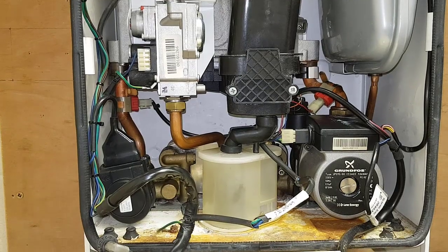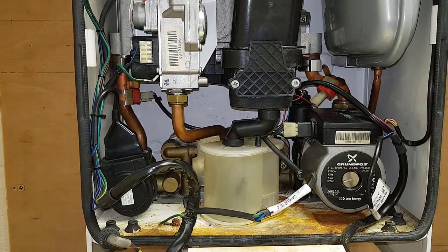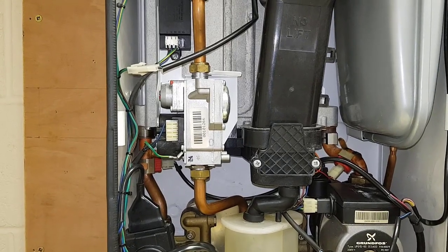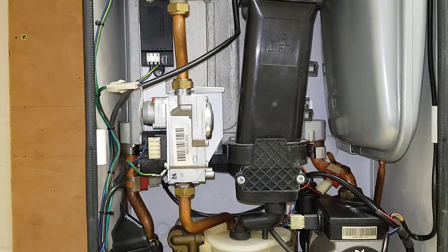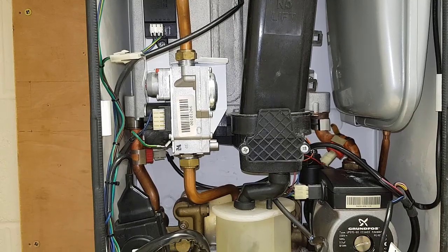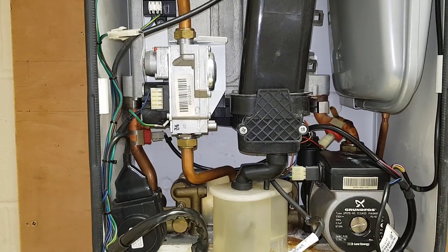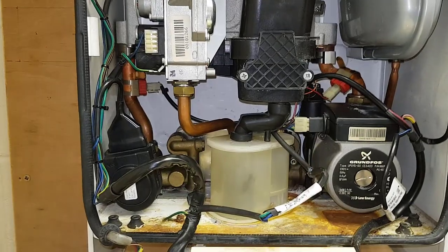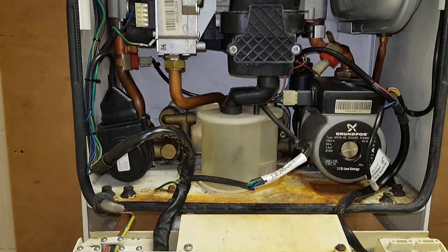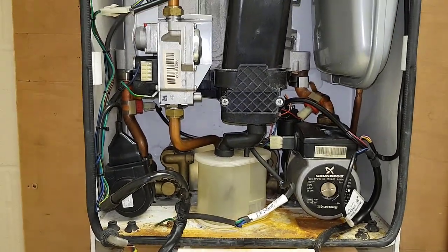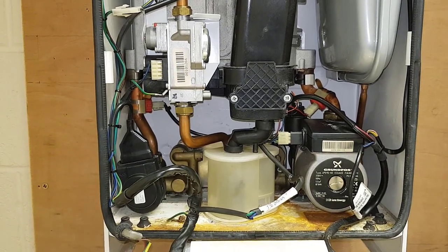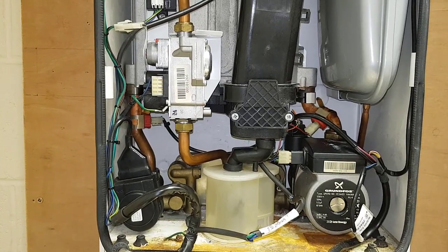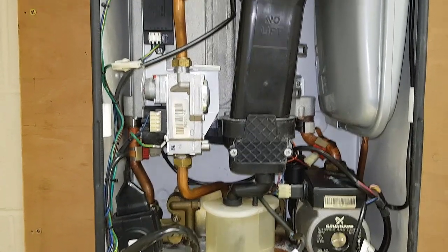Check the pipe work, check the main heat exchanger, see if there are any cracks or holes, check the filling loop, and again the plate heat exchanger. Yeah, that's it, correct. So basically we've just done an overview of the fault analysis quadrant. This is a guideline, a framework you can use for your diagnostics, especially for new engineers.